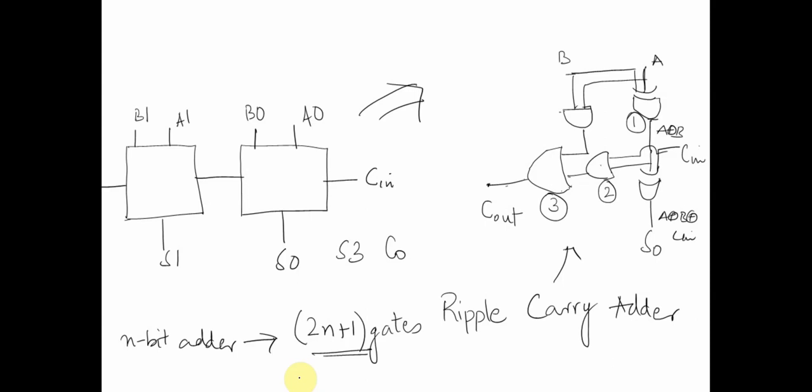So this is a pretty slow method of implementing whatever 4-bit adder we did, right? However, there is a faster way to do this computation, and for implementing that circuit we have something called a carry look ahead generator. And in a carry look ahead generator, what we try to do is create two terms.